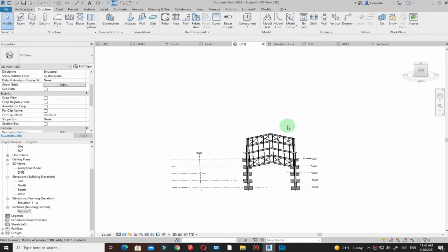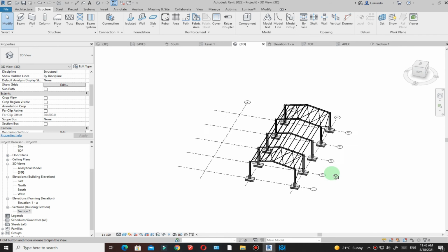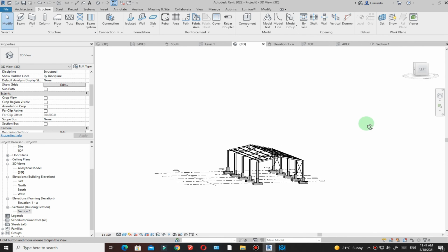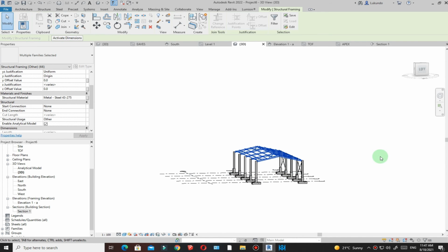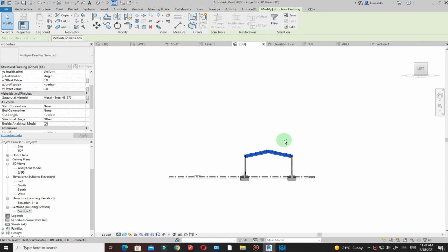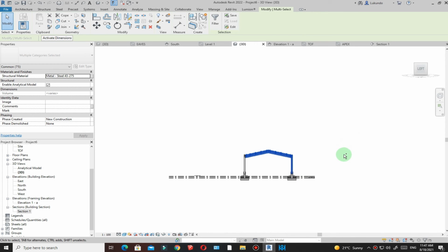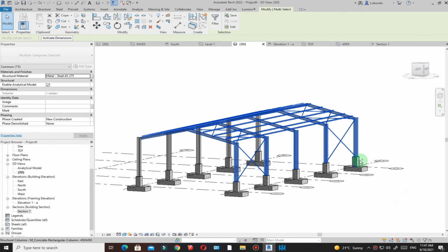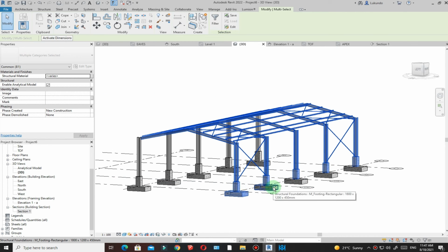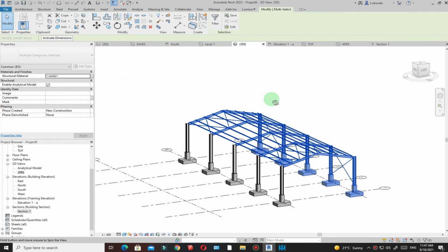Now I just need to copy this frame on the other side. So what I'm going to do, I'll orient it somewhere there. Make sure that I select the members, except the columns here. So I'll orbit like that, holding the shift, then orbit like that. And make sure that you select, I'll hold Control to select, the columns, just like that. Select that one, that one, that one. Make sure that you don't select your grids. Okay. So that part of the frame is selected.